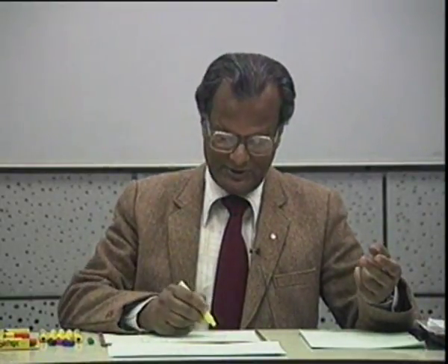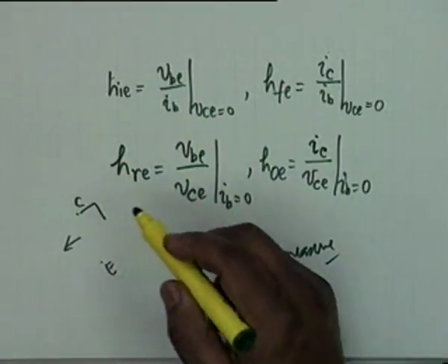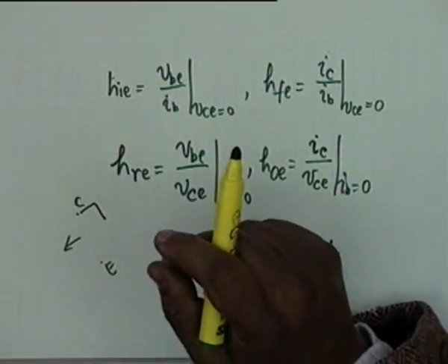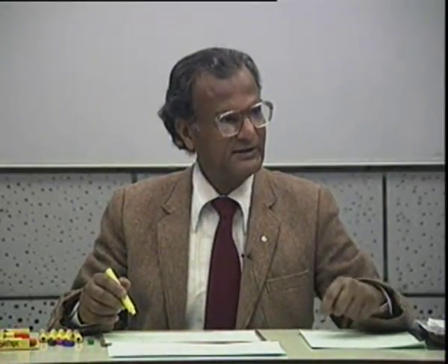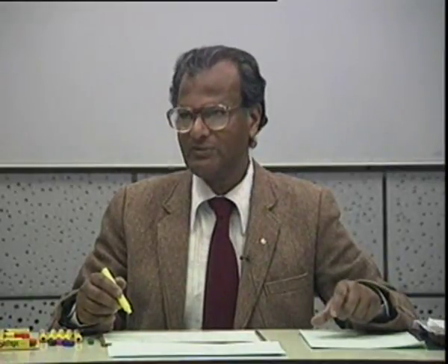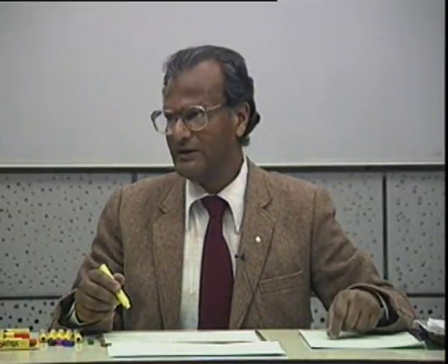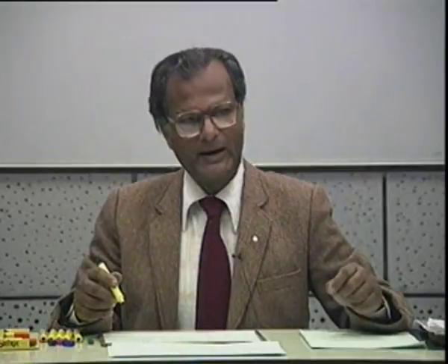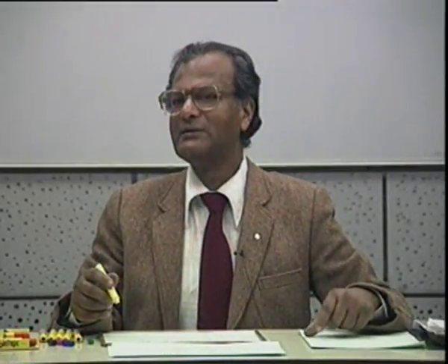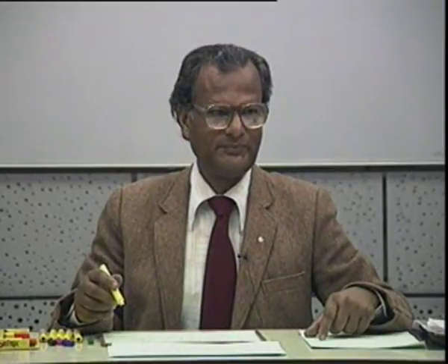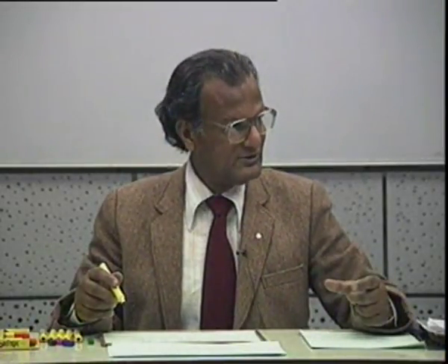And therefore, between collector and emitter, even if you introduce a 1K resistance, it acts as a short circuit. Isn't that right? It is very easy to short circuit the collector emitter terminal, because the impedance faced by an external source at the collector emitter terminal is very large. If you have a very large impedance source, it is very easy to short circuit this.